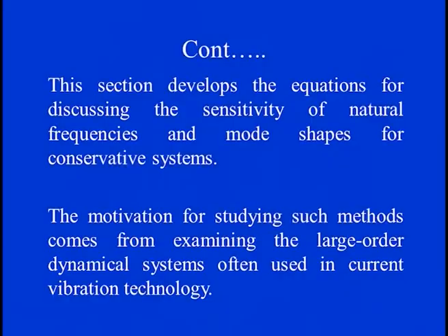So we need to see how the parametric variations or changes are to be incorporated, so that we can go for recalculation or reanalysis, and things are more effective in terms of structural modification. In this part, we again need to generate the equations according to the changes, and discuss the sensitivity of these changes on the natural frequency and mode shape, meaning the eigenvalue and eigenvector set for any conservative system.